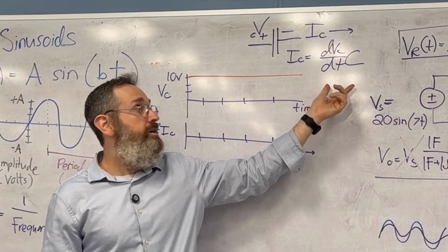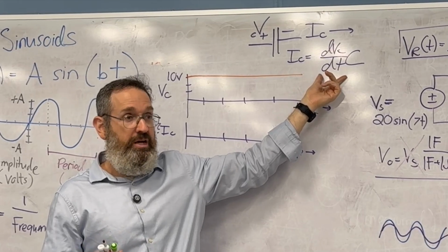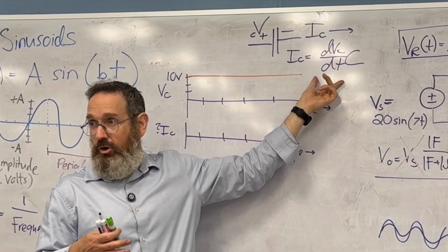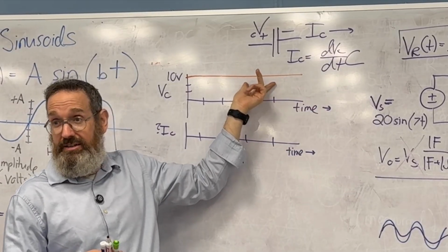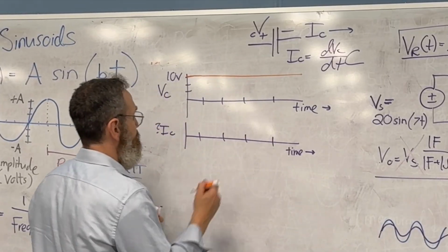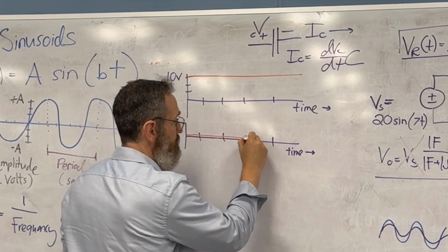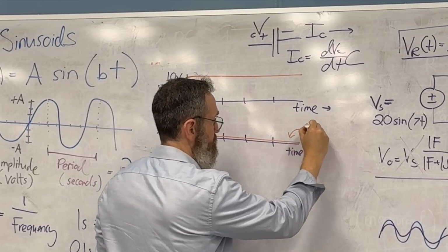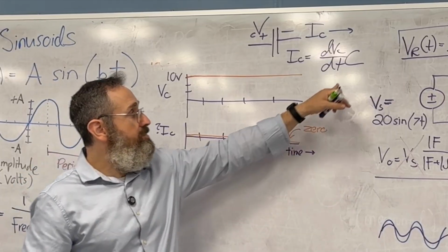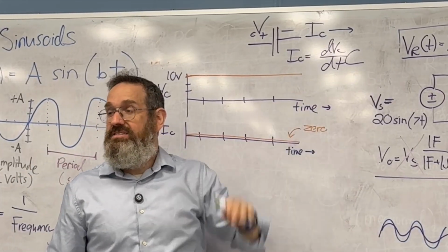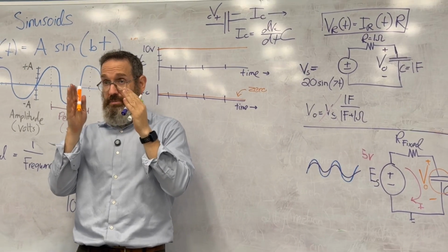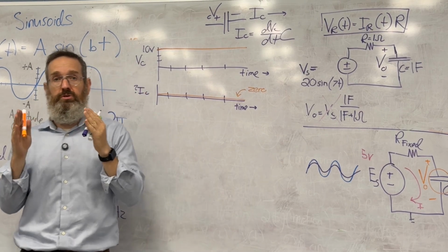Maybe put it another way: the voltage is not changing over time. The amount of voltage change over time is 0. All these things are true, however you want to get it. So what that means is that the current in this case is 0. Now you'll notice that this 0 doesn't depend on the capacitance. It's 0 no matter what. If you put a 9-volt battery across the capacitor, there will be no current flowing across the capacitor.